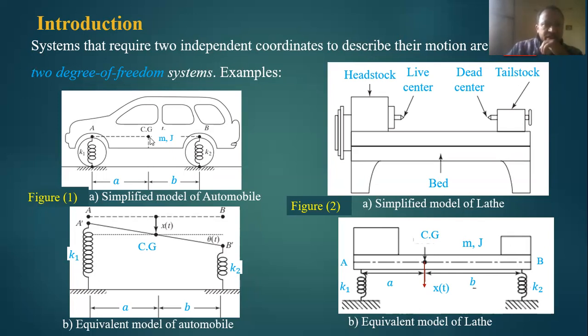okay, so taking CG as the point where all the vibration will take place. On that, we consider the motion to the front side and motion to the back side of the car as a kind of degree of freedom, or we can represent it in terms of the rotational motion of the center, as well as the linear motion of the reference point, the CG point.